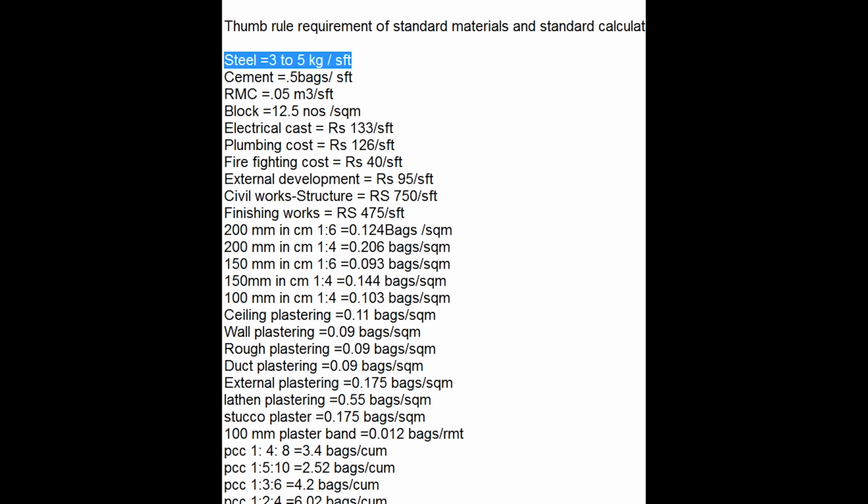For a multi-story building or commercial building, the FSI allowed is more. For commercial buildings, in some areas the FSI allowed is 3. For a multi-story building, generally the minimum plot should be 5000 square feet as per the municipality rules.